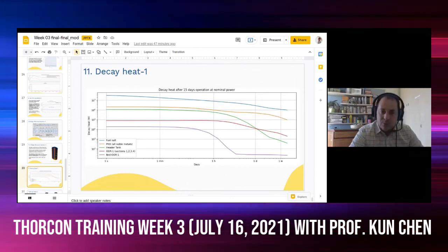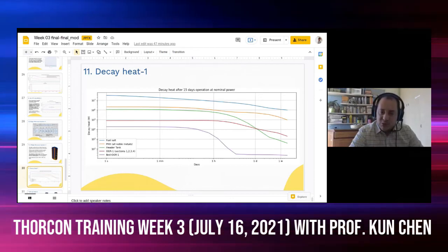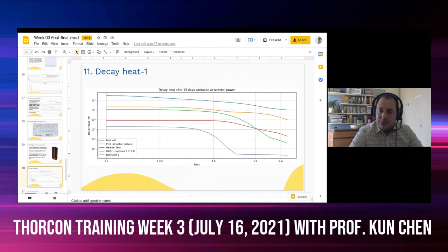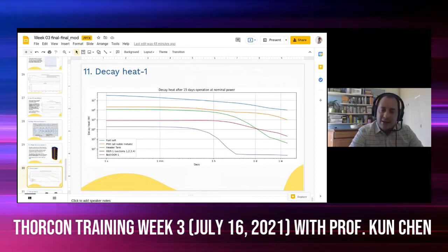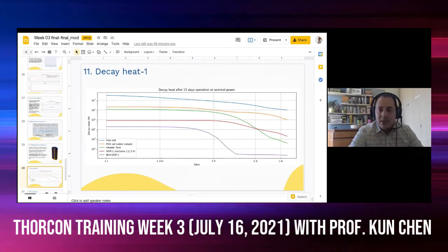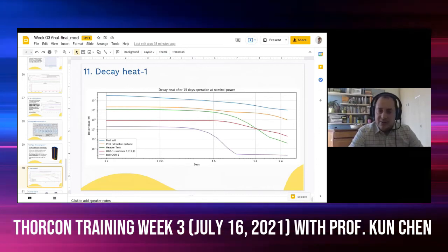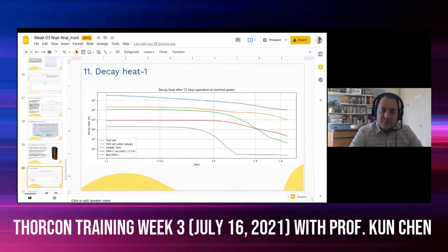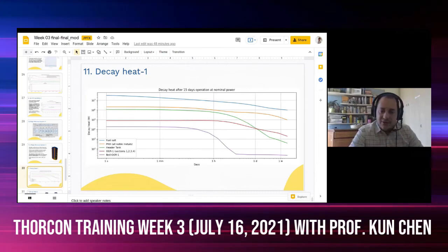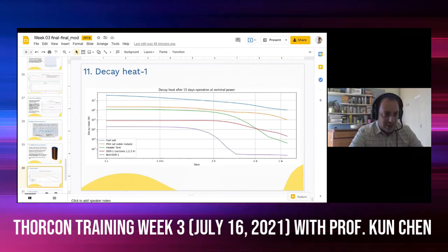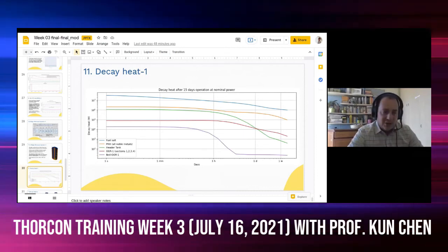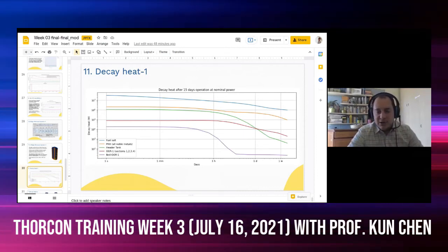The flow distribution is controlled by both accurate gap sizing and localized pressure drop or orificing in the plates below or above the logs. So that has been taken into account correctly. So as you state, it changed the flow distribution, it does not have a huge impact though.